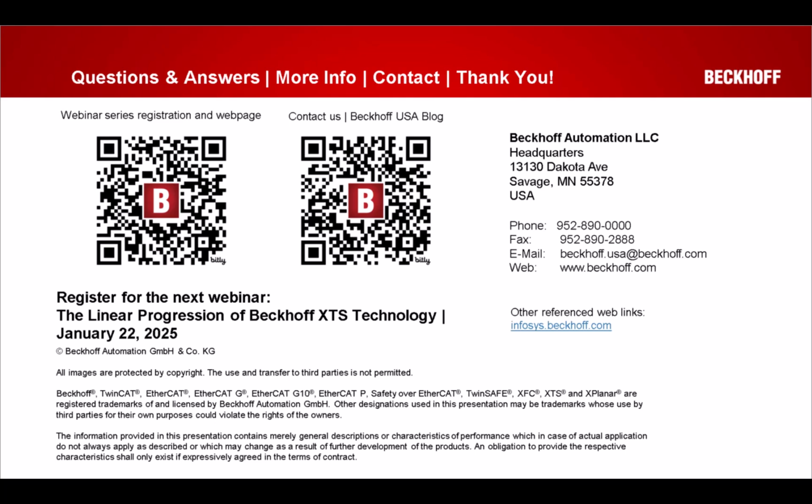I know that we have a library as well that supports that, but it's for like positioning algorithms. Otherwise, yes, a third-party software could be utilized as well, like a MATLAB Simulink with an interface or as a TcCOM object, which would function real-time in TwinCAT as well. So we do have a couple options on that front.